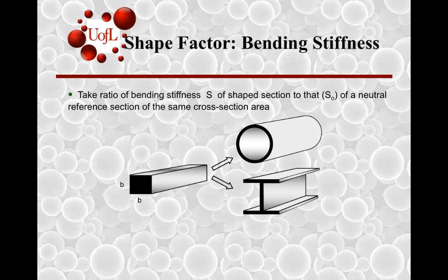So when we are looking at a stiffness limited design in bending, we came across a shape factor phi that was defined as the ratio of the bending stiffness of a target section, such as this tube or this I section, in reference to a section such as the square shaped cross section that has the overall same cross sectional area.